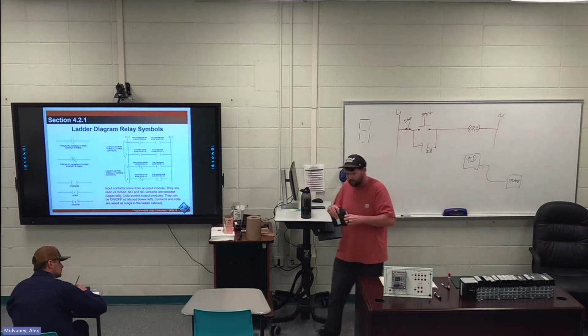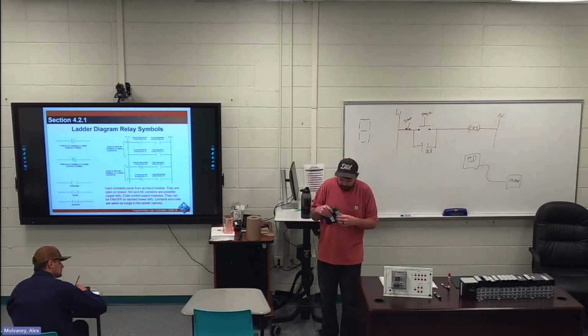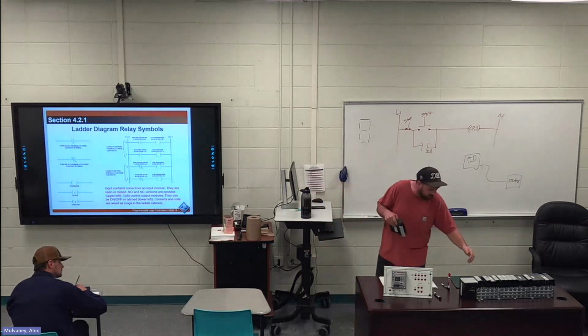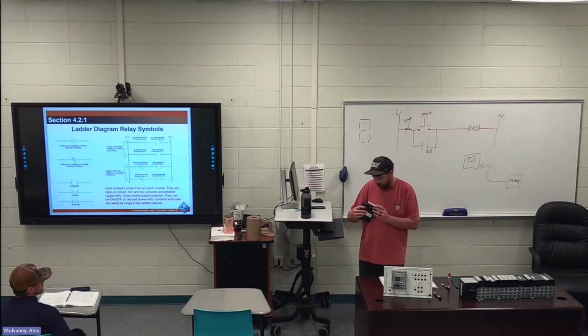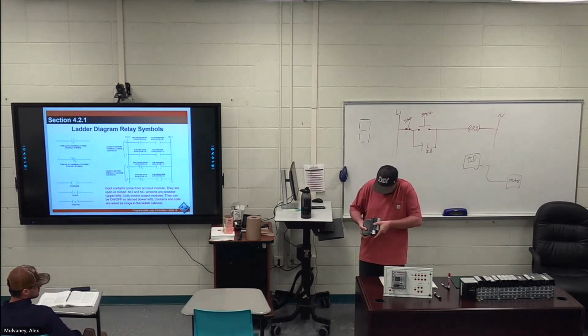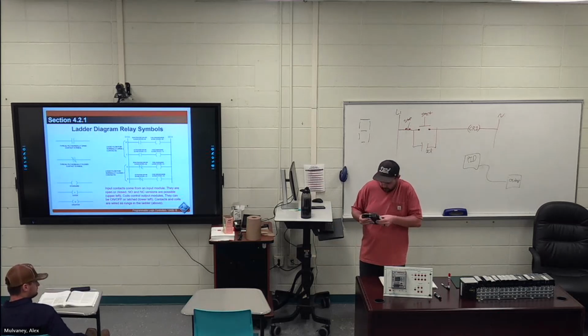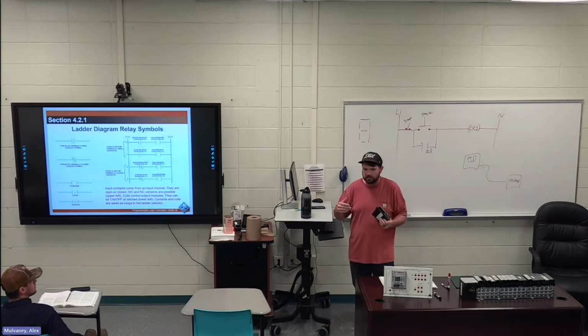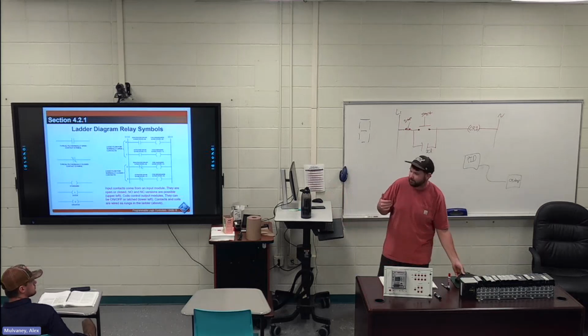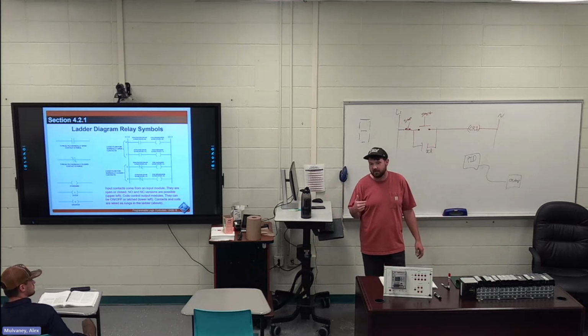If you have stuff like that, with the data transfer, you have to tell what's talking to the processor by what slot it's in in the back. But the wiring, you can leave wired up. All your wires stay on this, and then you put a new card in the slot, plug that in, and it's good to go. So it's actually pretty easy, because if you ever get to the place where stuff like that's happening, you're telling your operators what you're going to do.